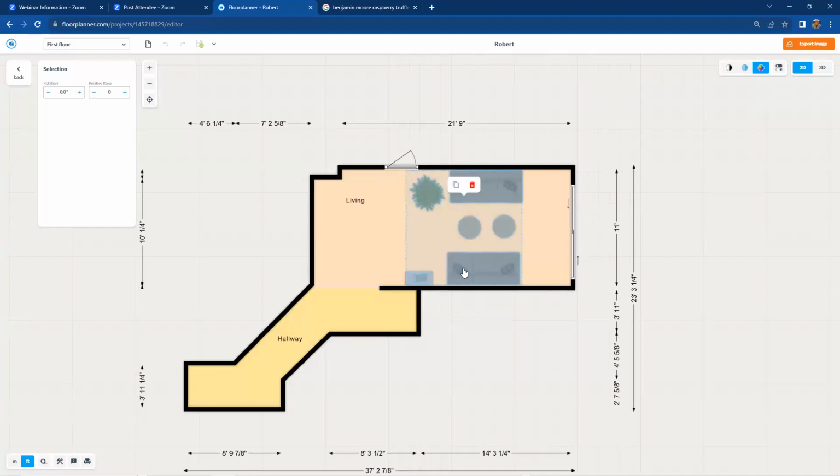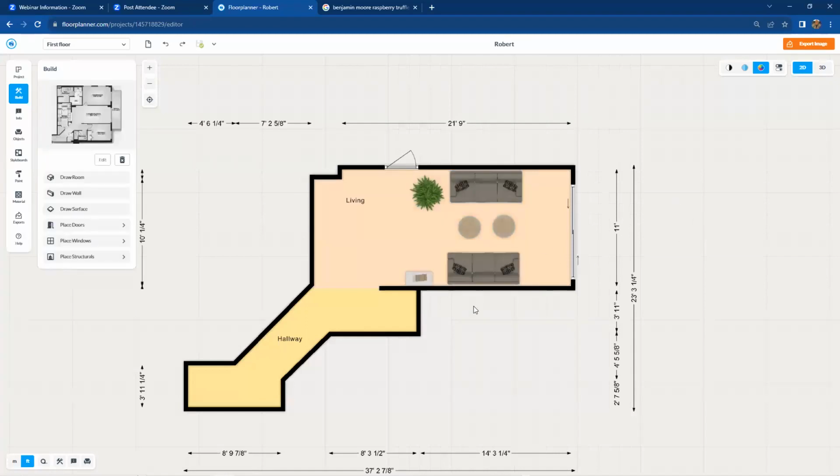If I wanted to select the structure for some reason, to modify it, delete it, or copy it somewhere else, I would have to get the furniture and the fixtures out of the way. I could move them out of the way, or delete them, but you can also turn them off. There's a layering command for that in the upper right-hand corner under 2D settings, settings tab.